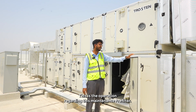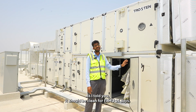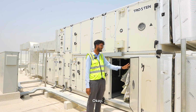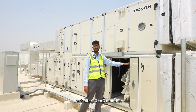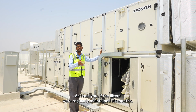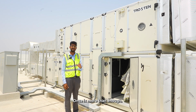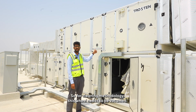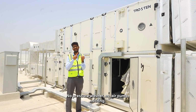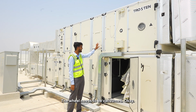This is the operation. Regarding maintenance, pre-filters, as I told you, should be cleaned. For the FAHU, once every 15 days the condition needs to be checked and cleaned. Back filters need to be replaced once every 3 months. For the sensible and enthalpy wheels, as I told you, if the filters were regularly maintained, once every 6 months is more than enough. For the cleaning methodology, the wheel needs to be vacuumed. No pressure washer, no air pump, nothing. The wheel needs to be vacuumed.